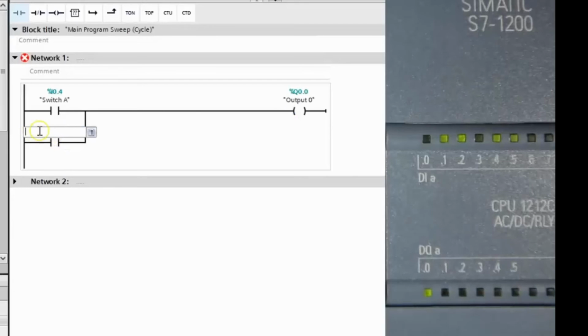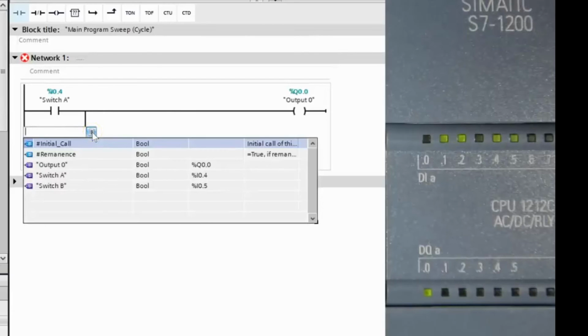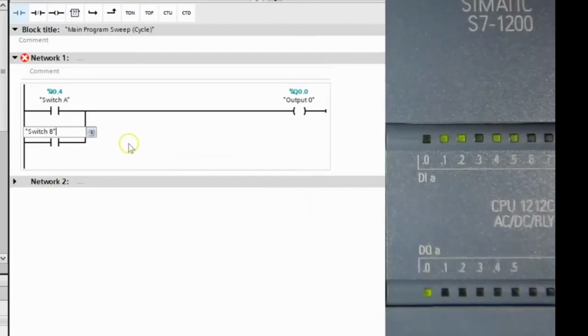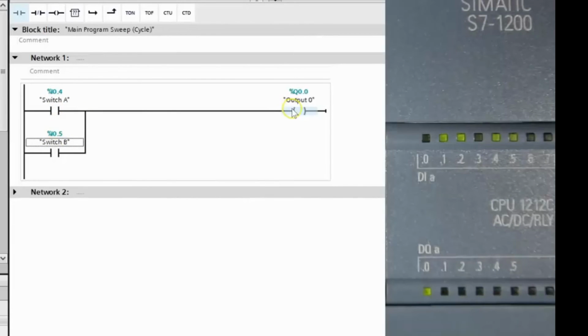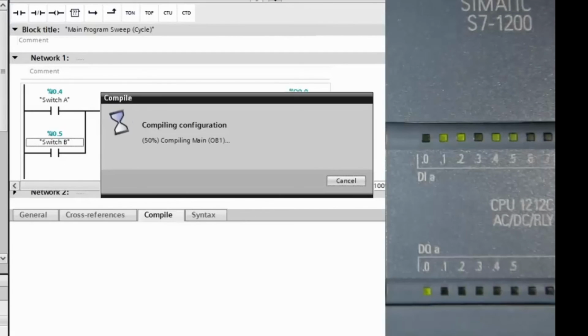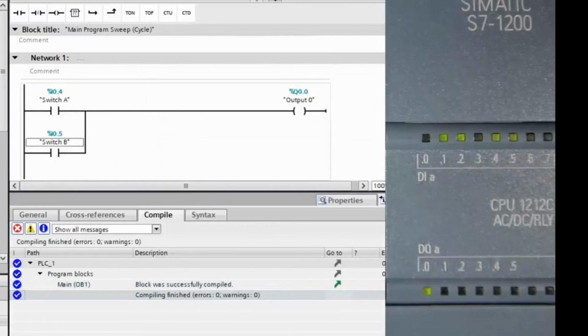So what we're going to do now is we're just going to switch up our circuit here. So let's drop this guy down so we can have a little bit more room. Okay, let's put in a parallel rung here. So we're going to put an open branch here. Okay, we're going to put an XIC, or what they call a normally open here. What I'm doing here is I'm left clicking here, bringing it up till I see green and let go. And now I've got a parallel circuit here.